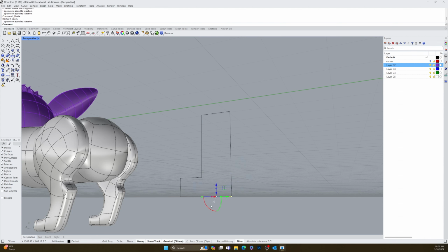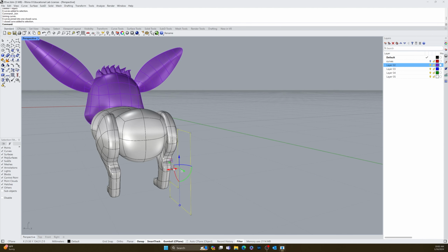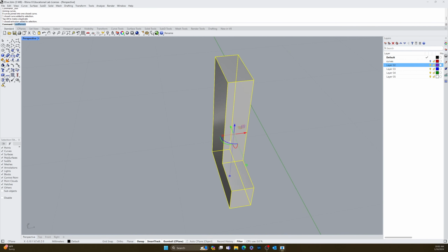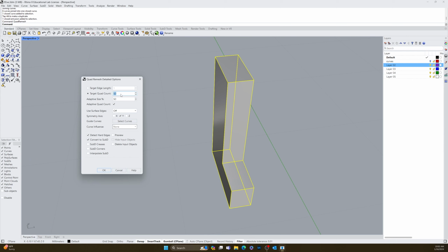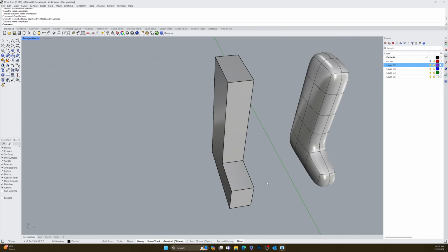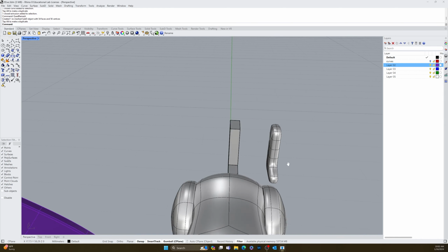That was part of the other rectangle from the top and the bottom. So it had double lines on here. Don't want those. So join them together. And now it should extrude. Okay. And I don't care if it's blocky because I'm going to do quad remesh, and maybe I'll do 40 instead just to see if it works. All other settings, keep it like that. Cool.